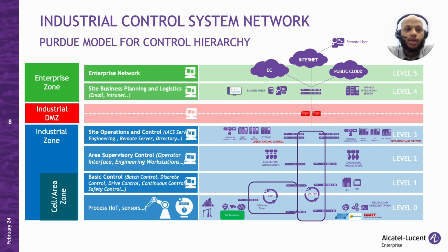So in industrial networks, the backbone network is commonly connected in a ring topology, while a star network can be used in the access layer. Ring topologies are commonly used in industrial networks due to their low latency and fast convergence times, and low cost, of course, for long distance wiring requirements. The site attachment can be designed as layer 2 or layer 3. We will provide an overview of the key technologies in this backbone network and site attachment options that provide the communication network which is able to provide resiliency, security, traffic segregation, and a high quality of service.